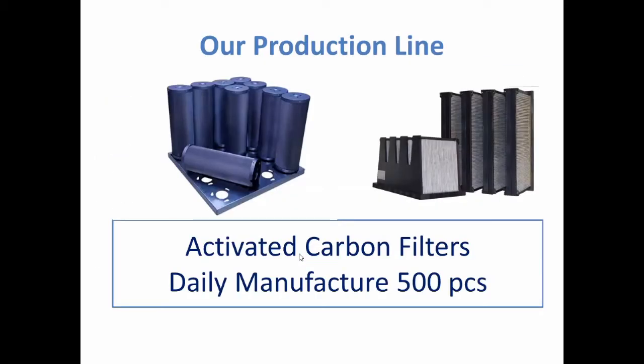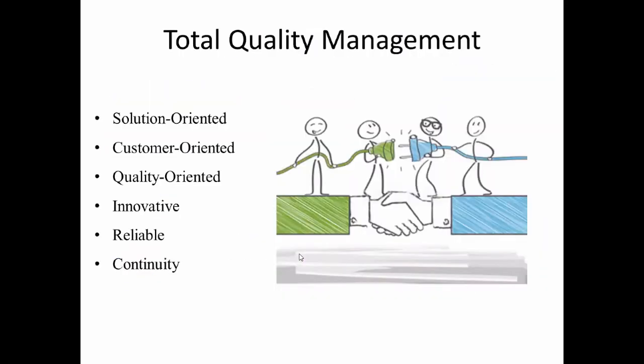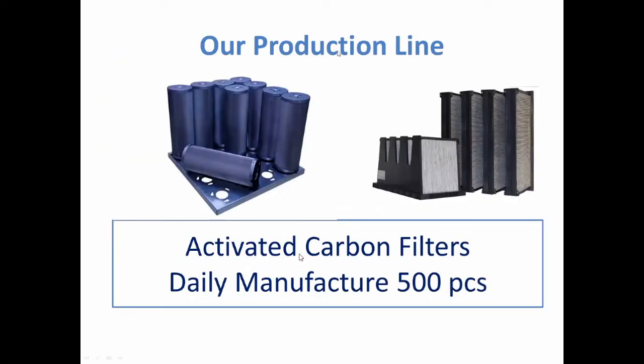And the other products, which are related to the carbon filters. You may know that the carbon filters for the small areas use a carbon filter as a cartridge or the V-cell filters. On the left side, you see the cartridge type, which is filled with carbon granules in a cylinder and goes with a plate. And this one is the V-cell filter with the carbon-plated media. So I will explain a little bit about the cartridge filter.